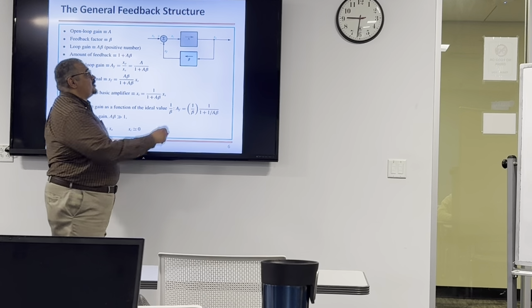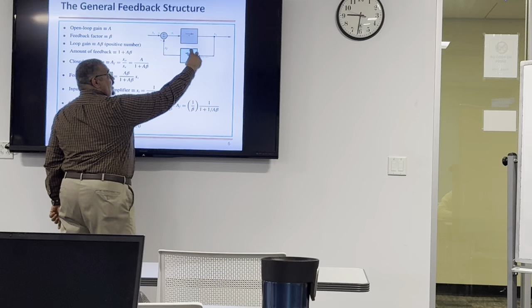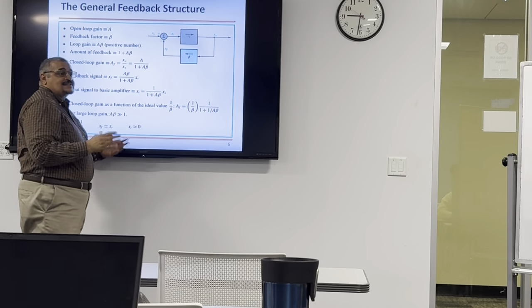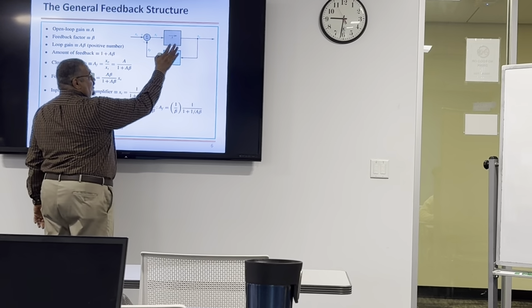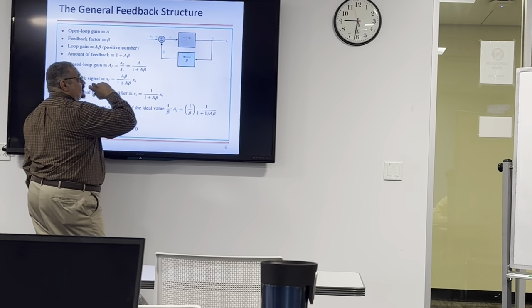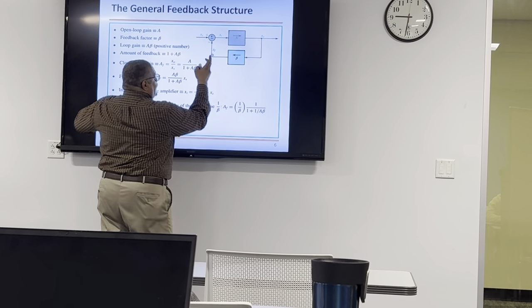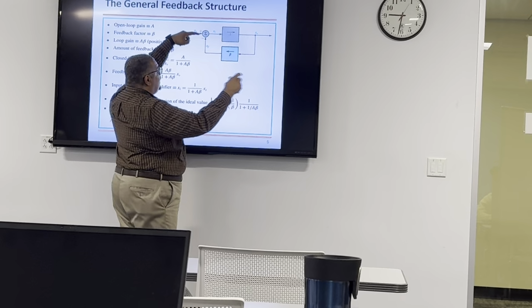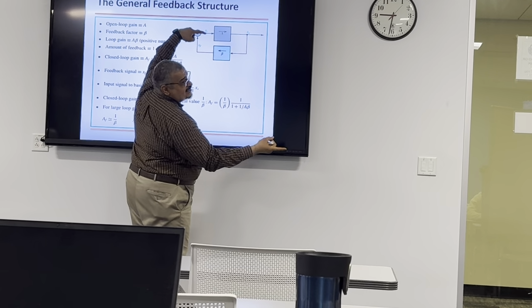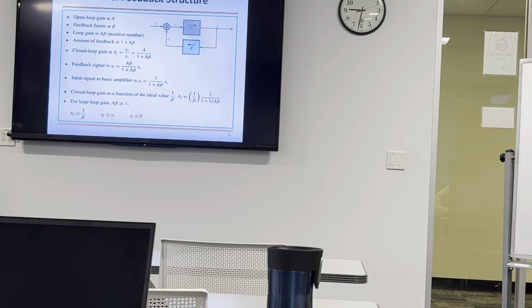Okay, so I measured the Vout and applied Vout into a network. Most likely this is a resistive attenuation network. It could be, by the way, frequency selective, but this is something else. Then the output of this, which is Vf, is subtracted from a voltage, Vs, to give you the input to the amplifier. Right? So Vi, what's Vi in this circuit?